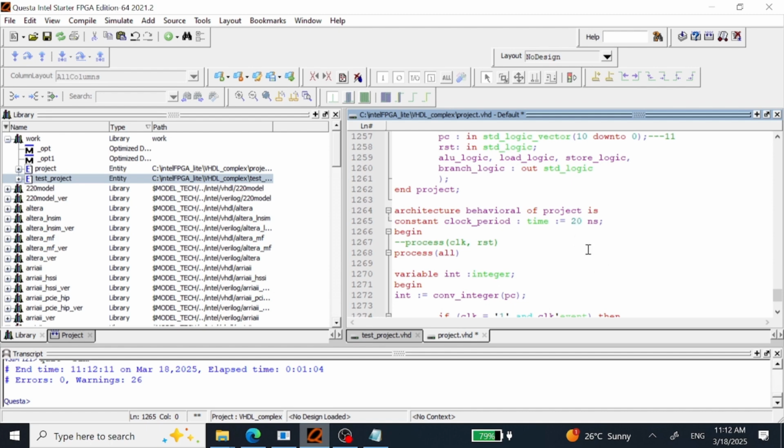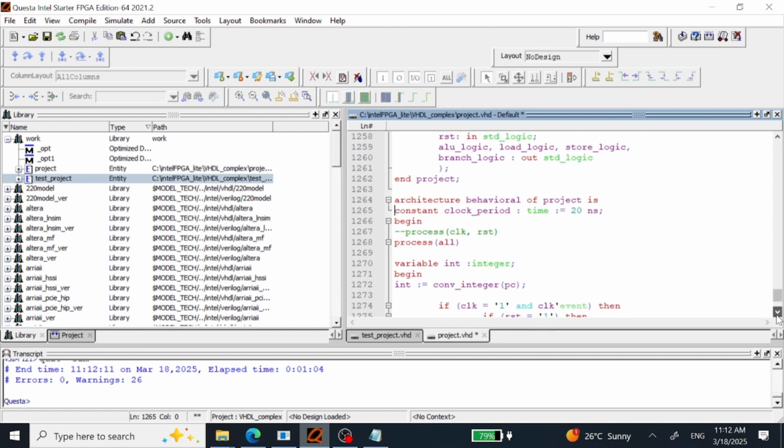So same clock cycle delay which we give inside the Testbench program, we are going to give here as well, because in VHDL we can't use the same clock which we get from our Testbench program. So we can define a variable using the same number of time units here, and we can use those.